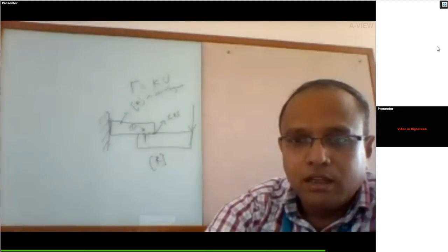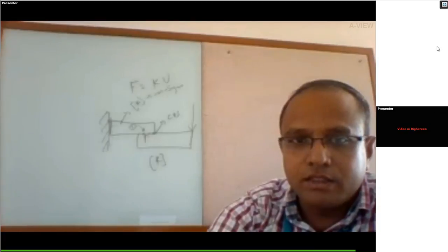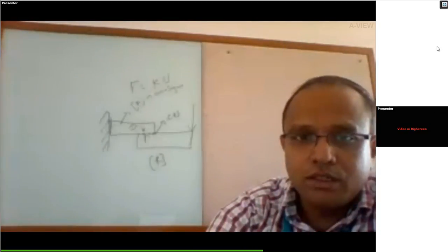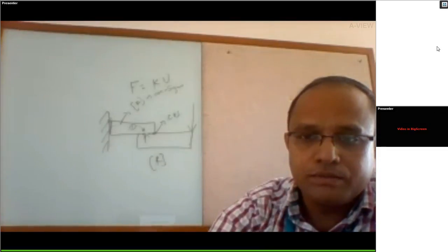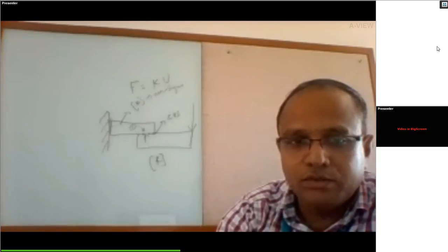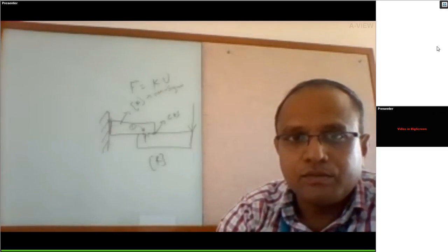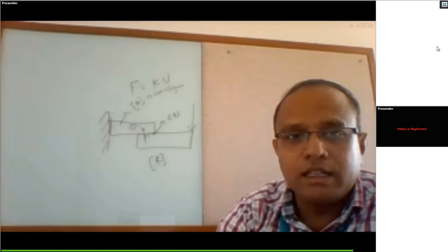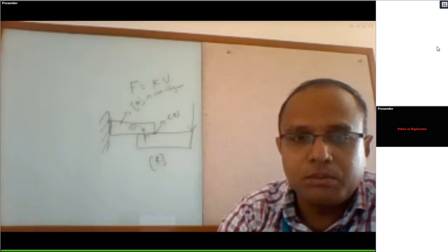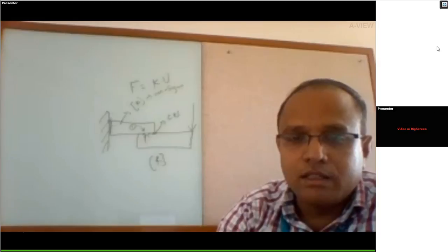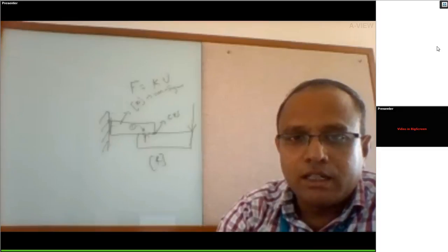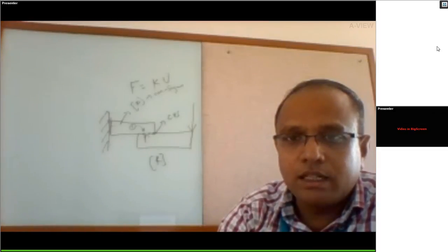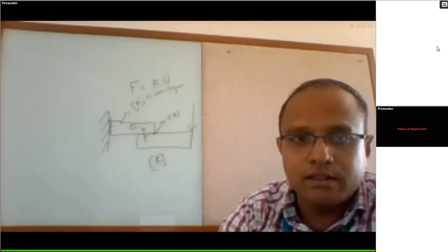With couplings and with constraint equations, we are not seeing much difference here. Couplings used a coincident mesh, and here we have used a dissimilar mesh between these two parts, and there is not much difference in the deflection. Couplings and constraint equations act like elements in that they increase the connectivity of the finite element model and therefore increase the bandwidth or wavefront of the system. What that means is that if you use couplings and constraint equations, the problem size will definitely increase, and at the same time the computational effort will also increase.